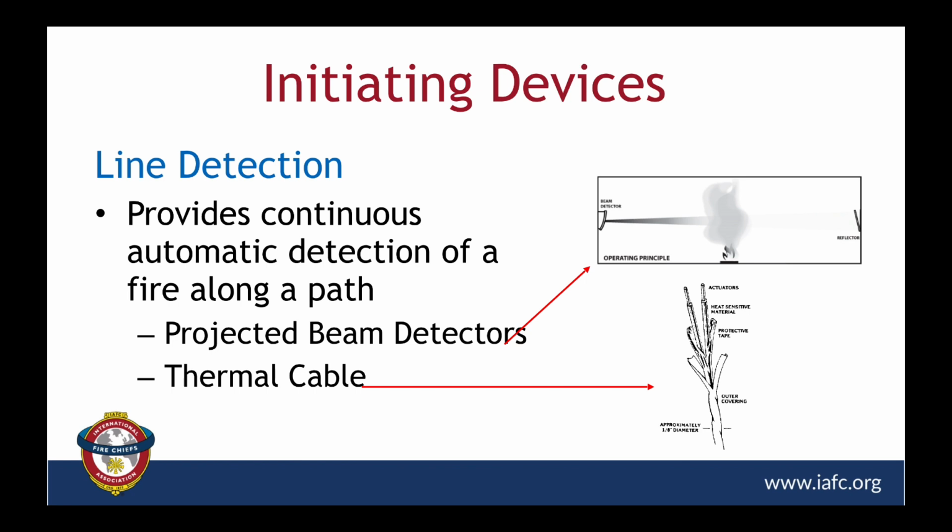The second type of heat-sensitive cable uses a single wire that is centered in a metallic tube, and the intervening space is filled with a substance that becomes conductive at a predetermined temperature, thereby allowing or establishing an electrical current between the tube and the wire.